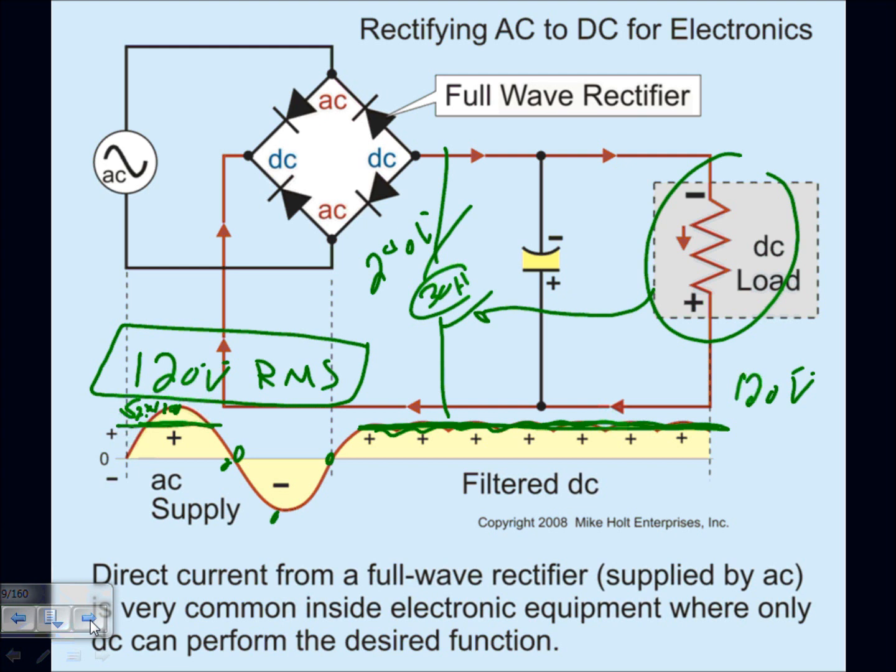So which voltage are you going to use for your calculation? Root mean square value, the effective value, which is equivalent to a DC. Just think of it this way: when I say 480 root mean square value, that's equivalent to a 480 DC line. Done. That's all you need to understand for all practical calculations.